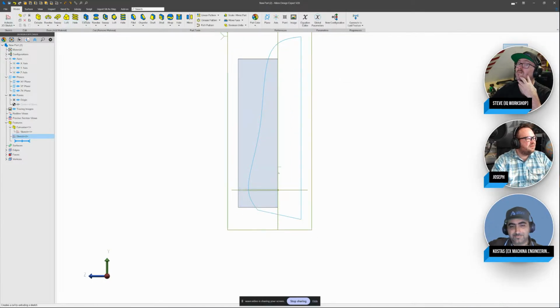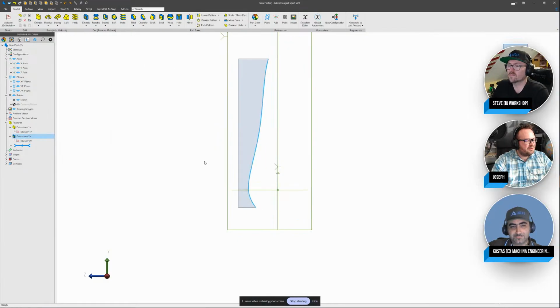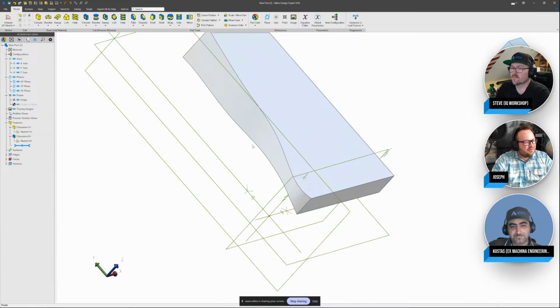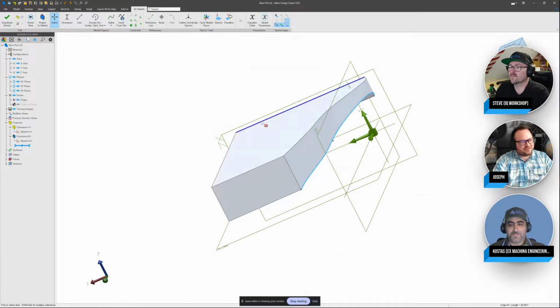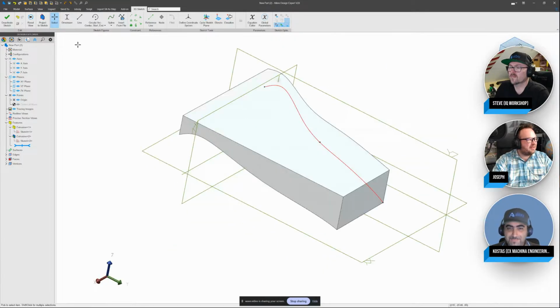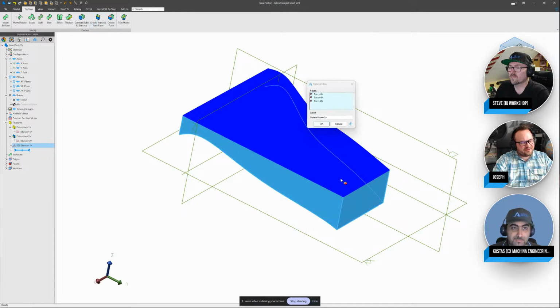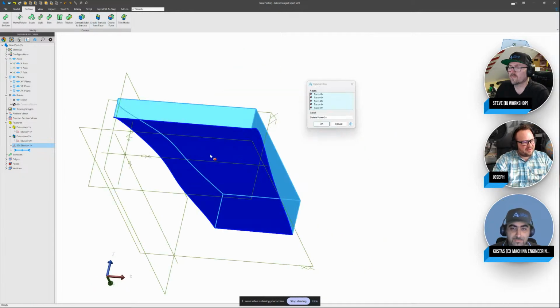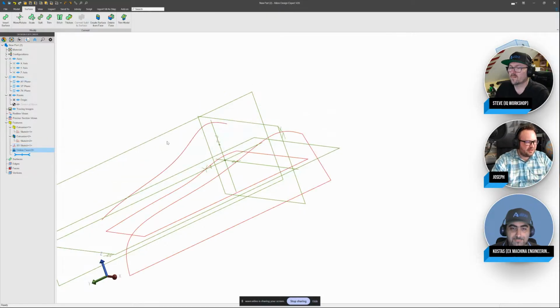and then we'll not extrude rather, but cut through that, through all. There we go. Now I can take this edge, we'll go to a 3D sketch, and we're going to say just make a projected 3D sketch of that edge so that we have that crazy path. Now I can go to my surfaces, and I'm just going to delete all these faces because I've used them for what I need, right? Just making a crazy 3D path.